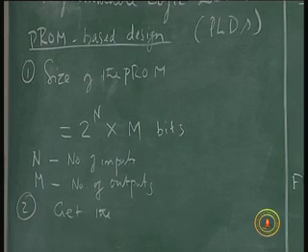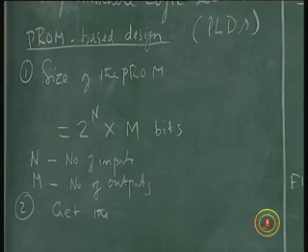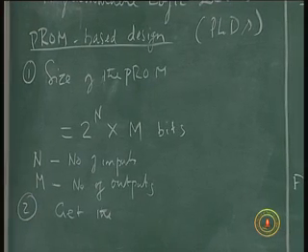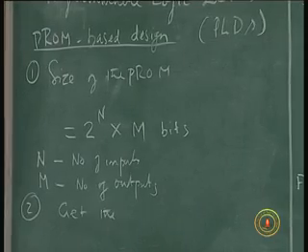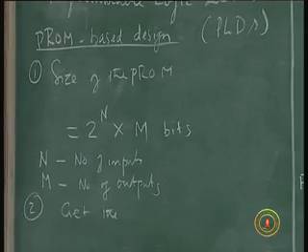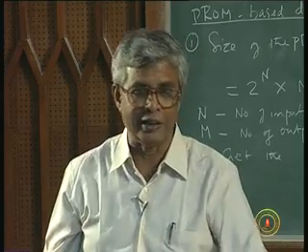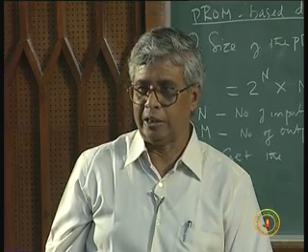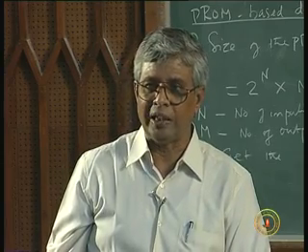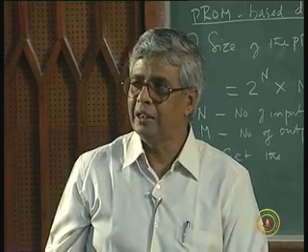ROM comes from the factory. Supposing you have an equipment in which everything is tuned and they don't want you to meddle with that, they will put a ROM. You cannot change it, you cannot erase it. Factory programmable it is called. ROM, when it is programmed in the factory and you will not be allowed to alter it.